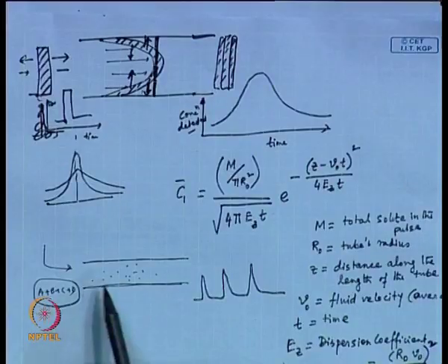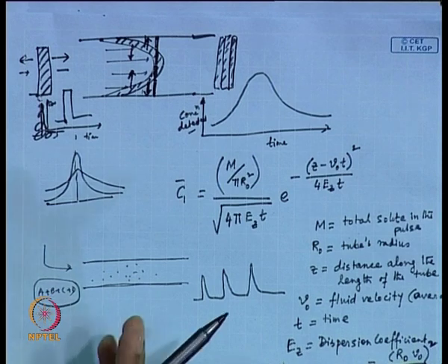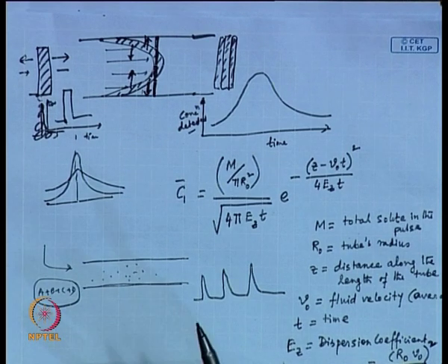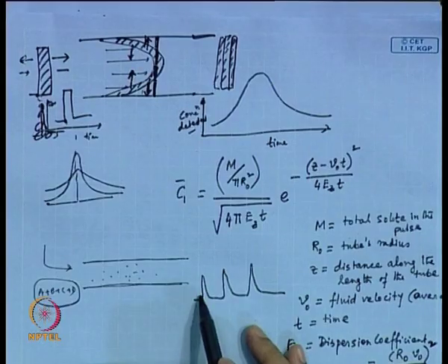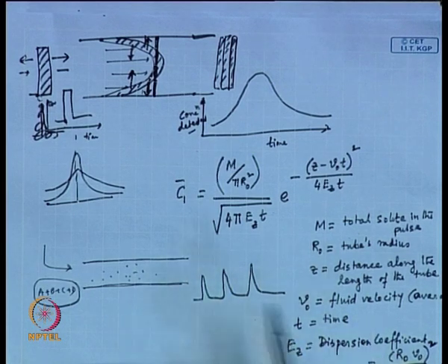So, these chromatographic units are very helpful in separating these components and then detecting them, and of course you have to first calibrate it. You have to send known samples and see where the peak appears, and then compare that with what you got for a real sample, and from there you can come up with what all components are there. Now, you should be getting these peaks, and each peak refers to A, B, C, D.